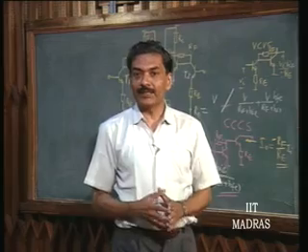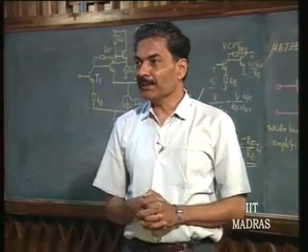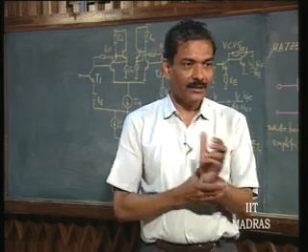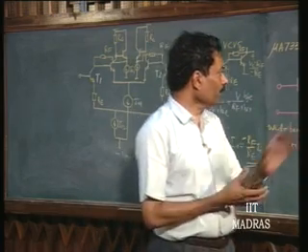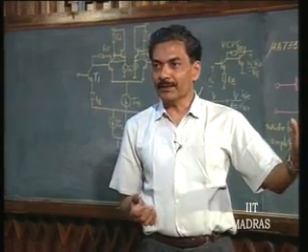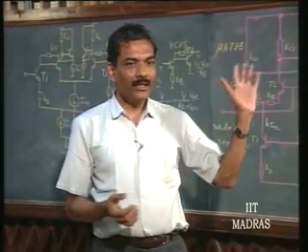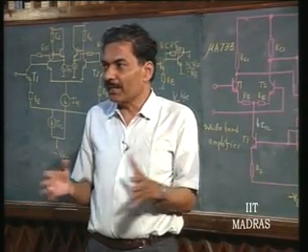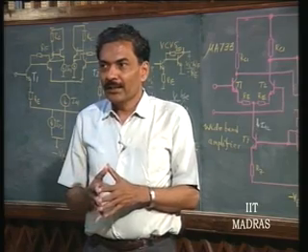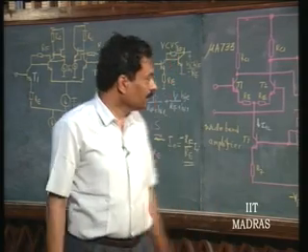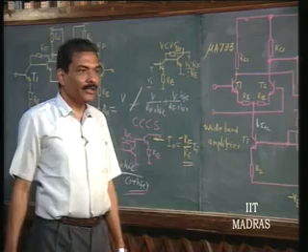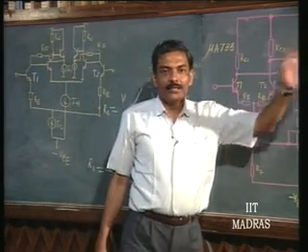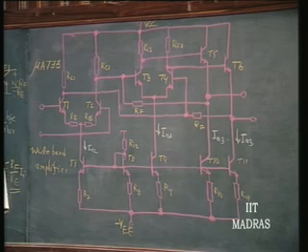Similarly for the differential structure, the output impedance depends upon RF and the HFE of the transistor. We know the input impedance, we know the output impedance, we know the voltage gain, we know all the small signal parameters of this wideband amplifier. You must also analyze the voltage swing, etc., because this is a wideband amplifier, it may be ultimately amplifying large signals, right?